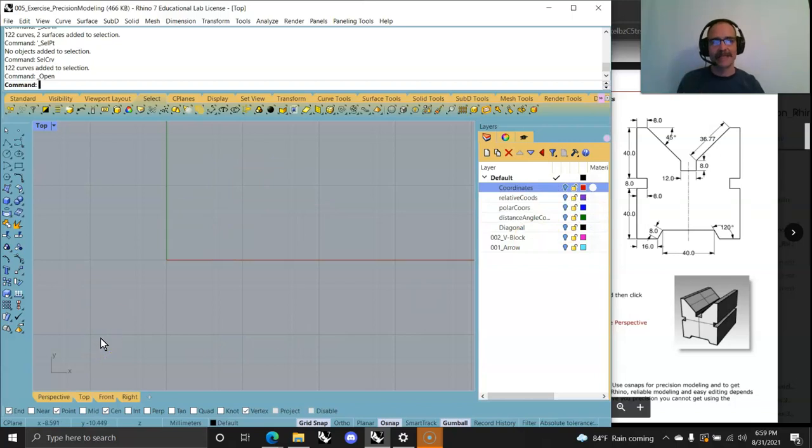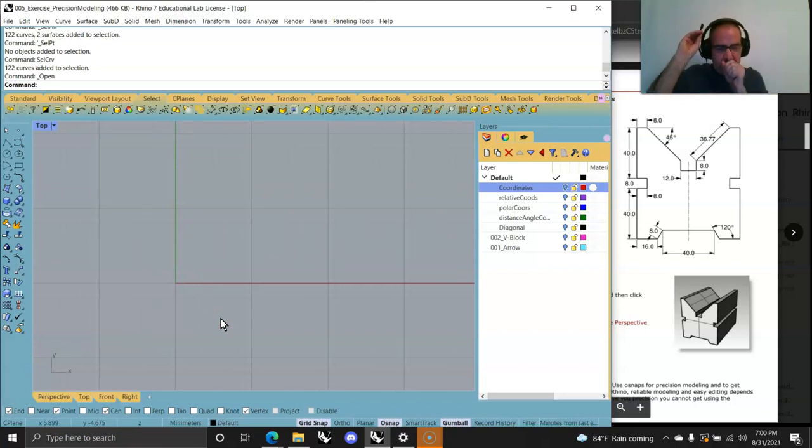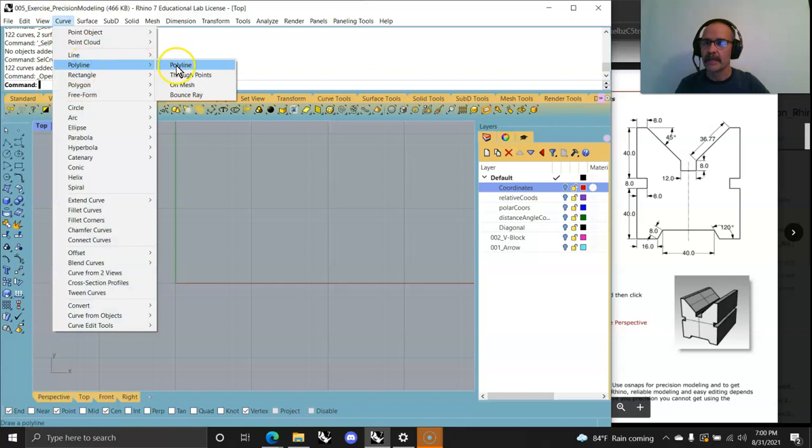The reason I'm saying this is doing surface edits and solid edits is crazy. It's going to weigh heavy. It's going to slow your computer. It's very heavy in Grasshopper. But if you can do all of your edits within a kind of curve sensibility and then lightweight extrusions, you're going to have a very fast script, and you're going to understand your work and work more historically like somebody on a blueprint. So if we go in here and we say nice and simple, curve, polyline, boom.